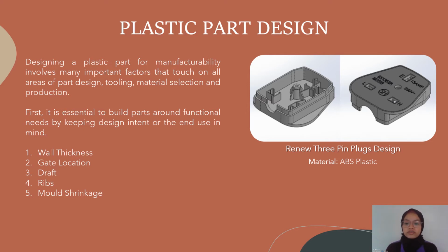Third, draft. Draft is the amount of taper on the vertical walls of the plastic part. Without draft, a part may not eject from the mold or may sustain damage during ejection. Typically, draft angles between 1 degree to 2 degrees are required, but can vary depending on the part restrictions and specifications.